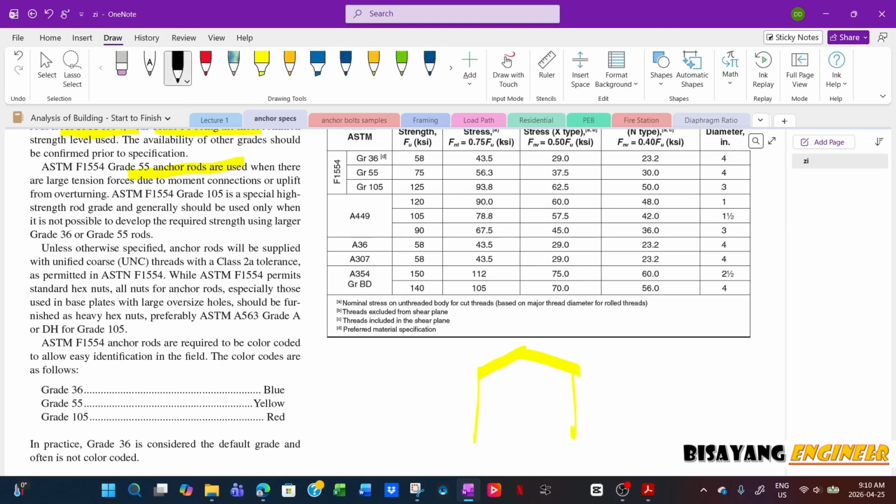Of course, vertical gravity, and I'm talking about the building reaction or the building load here, not the foundation reaction. So we have the vertical load, gravity, and then you have the uplift due to wind load, and then overturning, and then the shear.